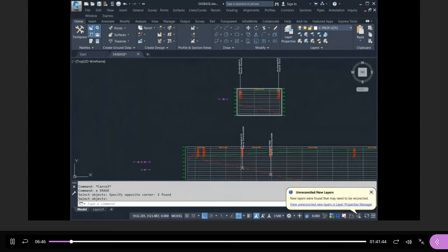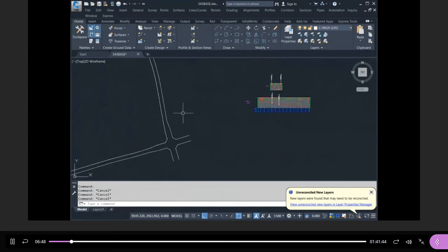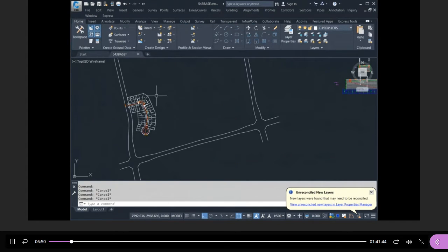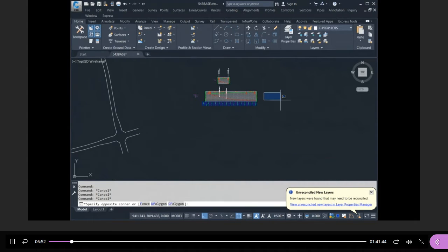So now what I want to do is I'm going to create my existing ground profile along the gutter on the cul-de-sac. So here's how you do that. And then I'm going to place it right on the end, at this end here. So I'm going to go to profile, create profile from surface. It's the cul-de-sac now. I'm going to see the existing road, add it.